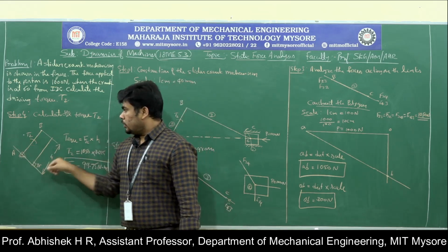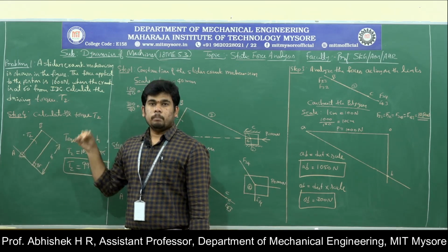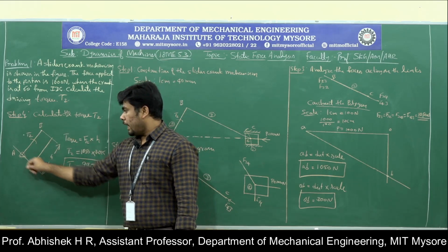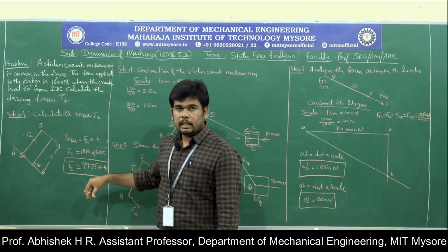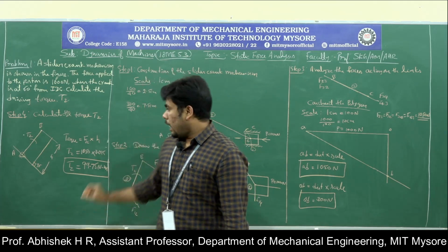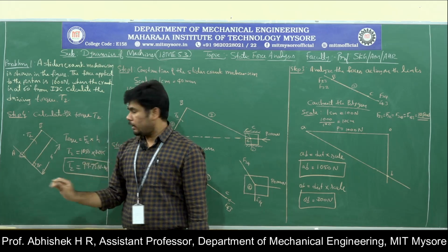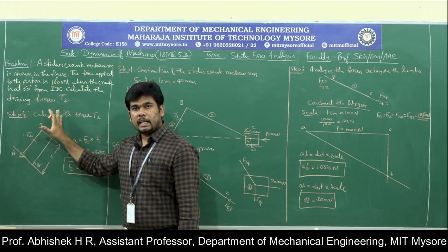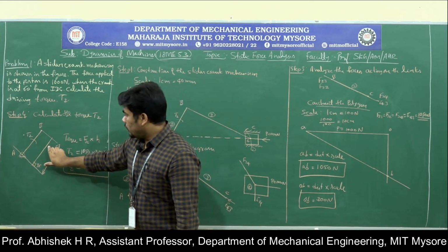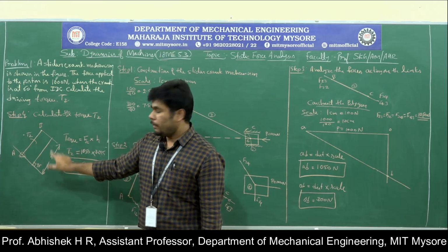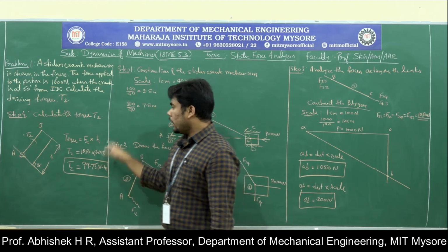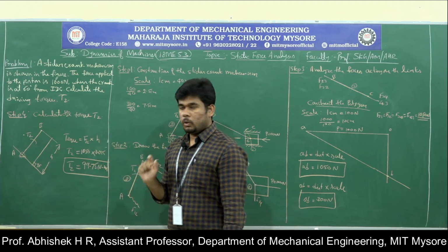Now just show the opposite direction, means the forces acting on the A and B, and on the extended line, whether top side or the bottom side, just mark a point. At that point, put your protractor, measure the 90 degree and draw a straight line. Then in your scale, measure this distance, that is the height of the link. So you will get around 94 or 95 mm. So convert into meter or keep it in mm also, no issue.